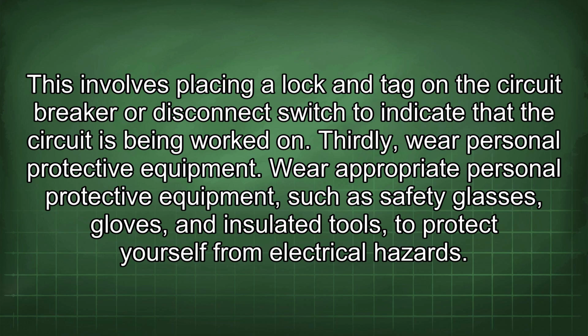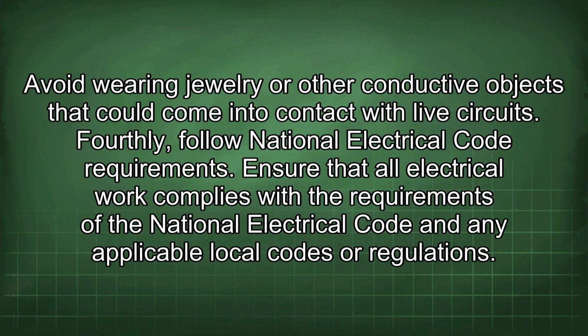Wear appropriate personal protective equipment such as safety glasses, gloves, and insulated tools to protect yourself from electrical hazards. Avoid wearing jewelry or other conductive objects that could come into contact with live circuits. Fourthly, follow National Electrical Code requirements.